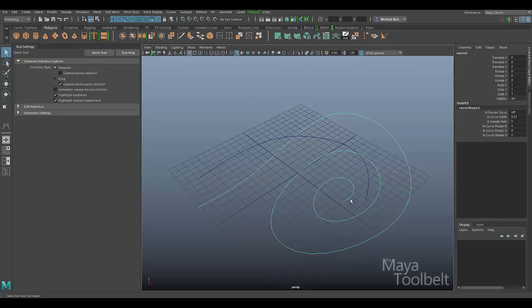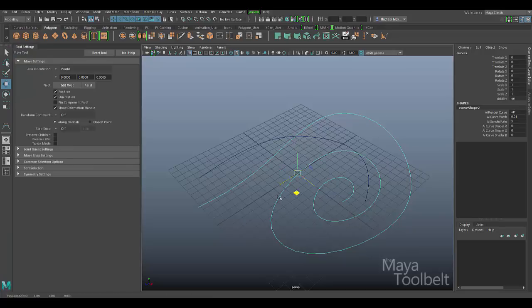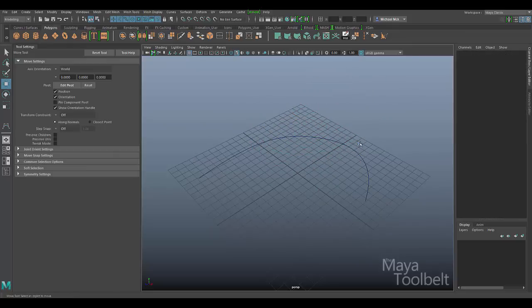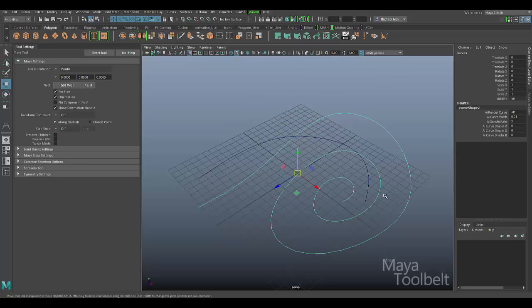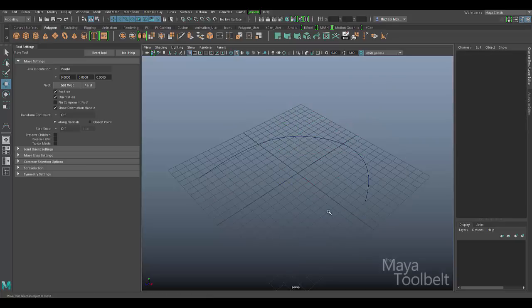So while the curve is being drawn, while the tool is active, the curve itself is not complete yet until you hit enter. Now after you hit enter, if you hit delete, obviously it deletes the whole curve, not just the last point. And if you undo, it'll undo the entire curve. So if you want to undo just placing that last point on the curve, you have to do it while the curve is being drawn, before you hit enter. I'll go ahead and delete this one.